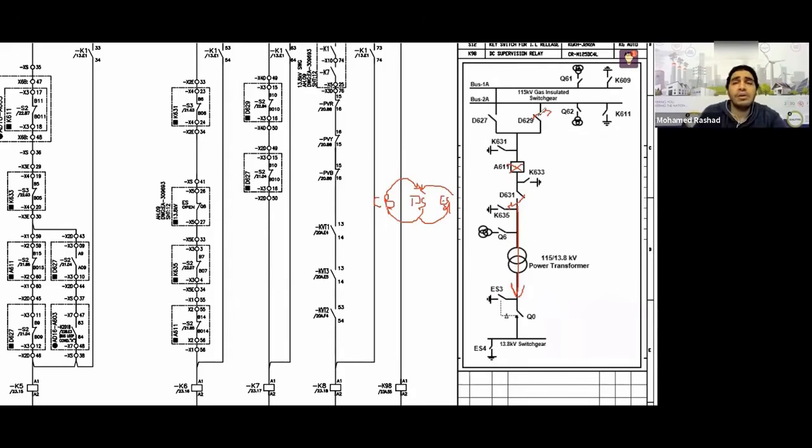But what do I want to do? I want to perform something called load transfer. Transferring loads from this bus to the other bus without affecting the load. Remember when we talked about choosing so that you maintain the system, there should be easy maintenance for different equipment and you minimize the outage during maintenance time, right or wrong? So we finished the same talk. I want my feeder as it is, to transfer it from this bus to that bus while it is closed without cutting the supply to my load.